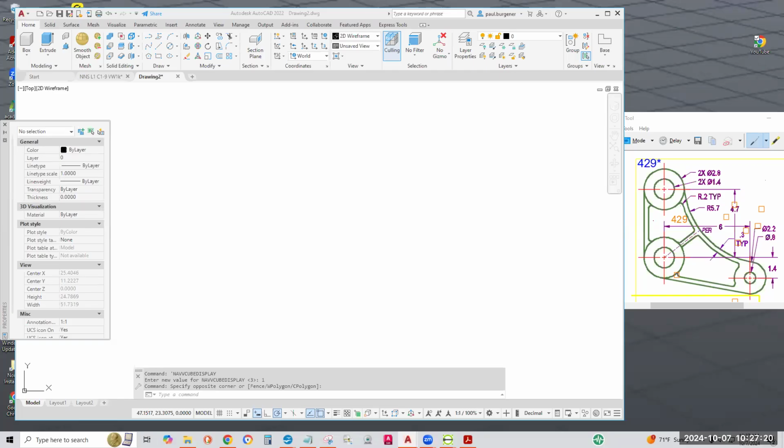In this video, I'll show how to do exercise 429 over here to the right of the screen. We'll first do it in 2D and then we'll extrude the three bearings or bosses, whatever. Oh, okay, forgot this one, but we'll extrude these to some value, extrude the webbing or the flanges to another value, and extrude the webs to a small value.